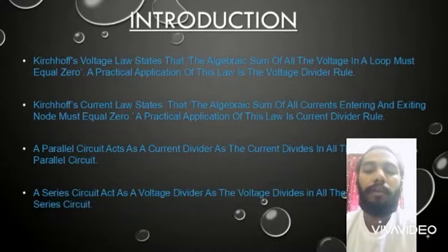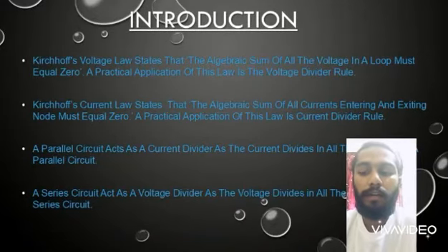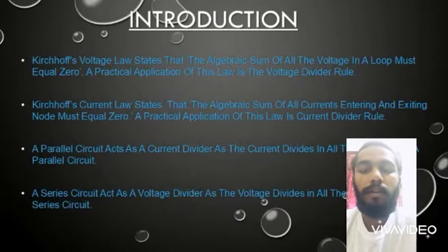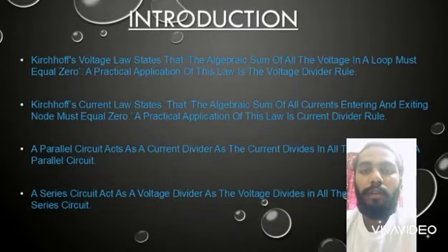Then the parallel circuit acts as a current divider, as the current divides in all the branches in a parallel circuit, while a series circuit acts as a voltage divider, as the voltage divides across the resistors in a series circuit.